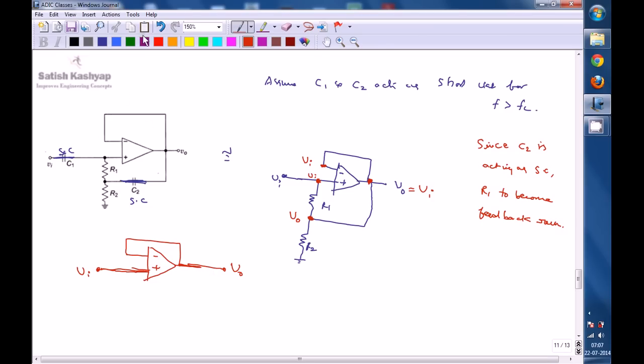Okay, now see, the input side is going to be connected with only R1, and R1 is a feedback resistor, so it has to be replaced with a resistor value of R1 divided by 1 minus ACL, that is nothing but the closed loop gain.